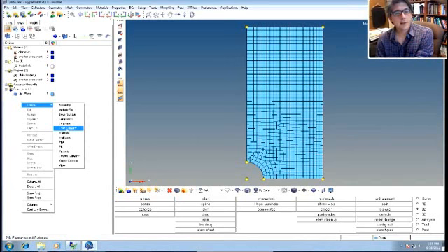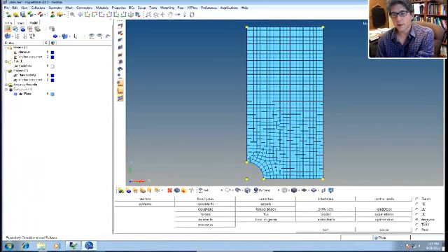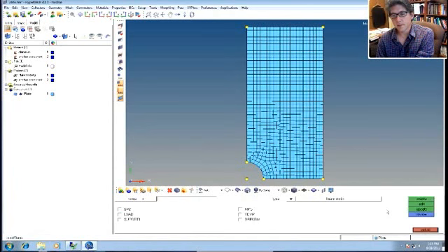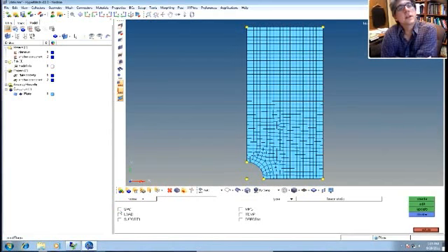And now, when one goes to define a load step, let me get a little ahead of myself. I go under analysis and then load steps, or up here to setup, create load steps. Remember, just like in Nastran, you specify what set ID defines all the SPCs and what set ID for all the forces that make up that particular load step.